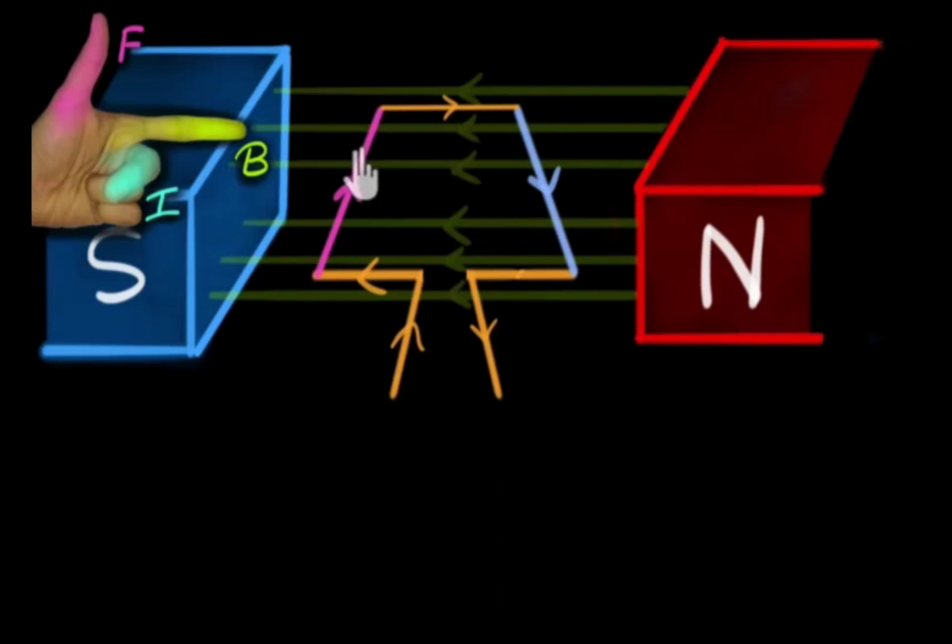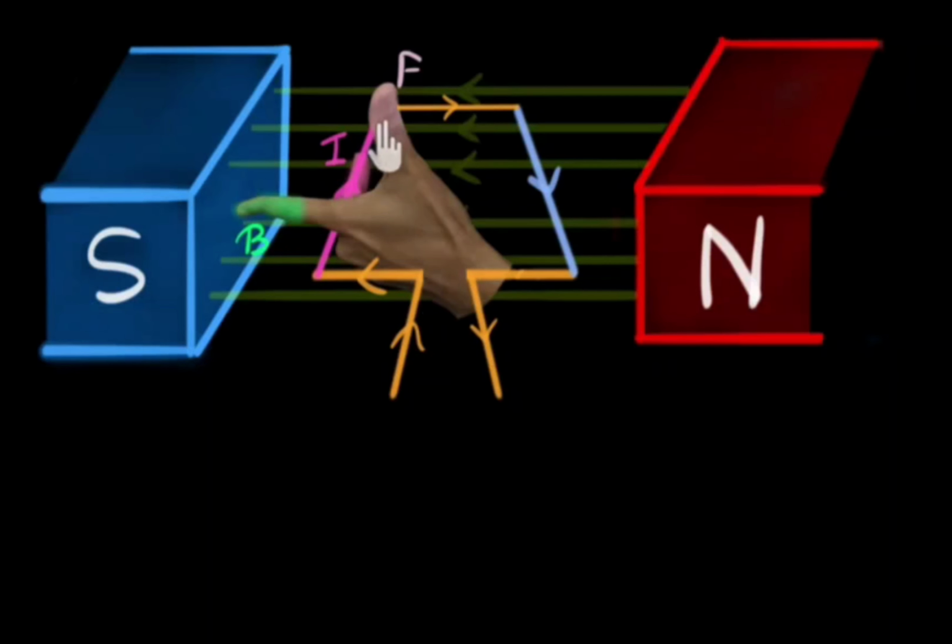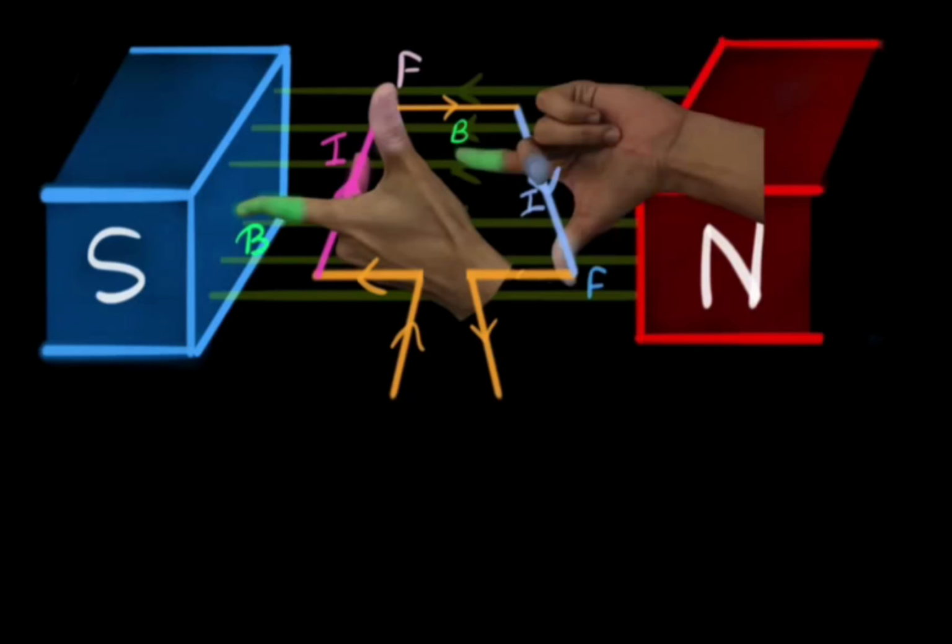This would tend to make the motor come to a stop, but two features let the coil continue rotating here. The momentum of the motor causes it to continue to rotate a little. A split ring commutator changes the current direction every half turn. This means that the current in the left hand part of the coil still causes a downward force and the current in the right hand part of the coil still causes an upward force.